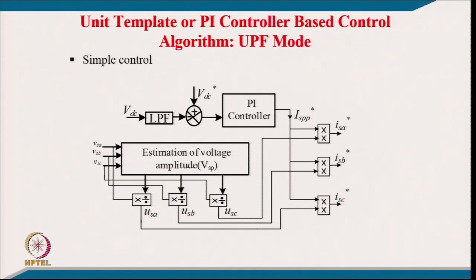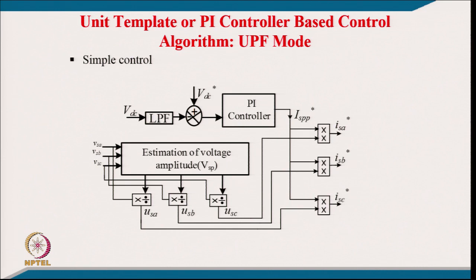We sense the DC link voltage, but if there is any unbalance either in the load or in the voltage, the second harmonic gets reflected as ripple at the DC link. It is the nature of the compensator, because this voltage source converter has to operate that way, so second harmonic ripple will certainly appear.